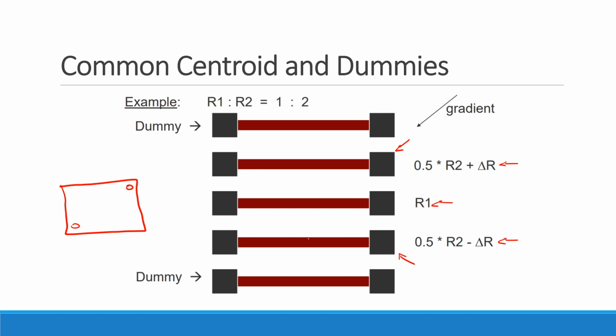So that if I add the resistance of this piece with that piece, it will indeed have double the resistance of what I wanted before. Okay? Of the center point, I should say. So again, this is so-called common centroid. This used to be really, really critical. Back when people were first doing analog design, basically if you didn't do this, you were completely dead.